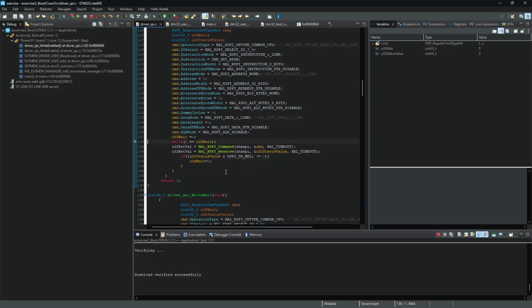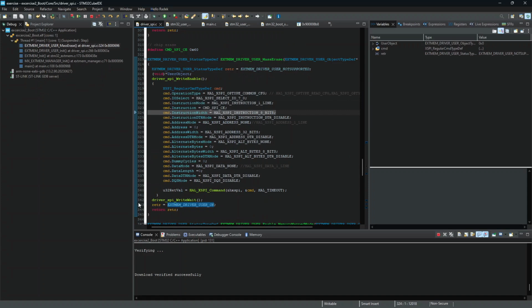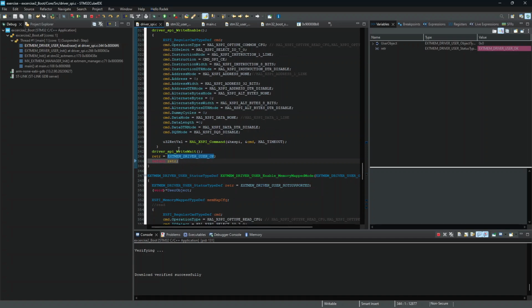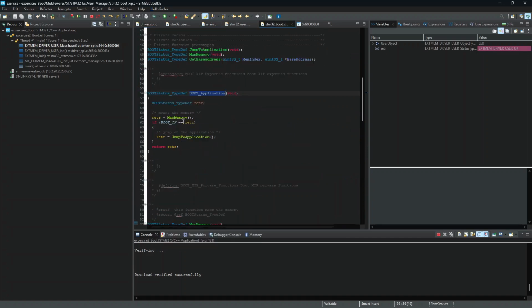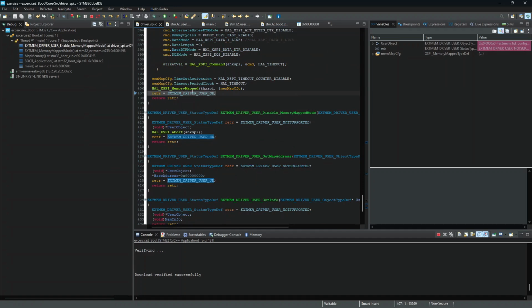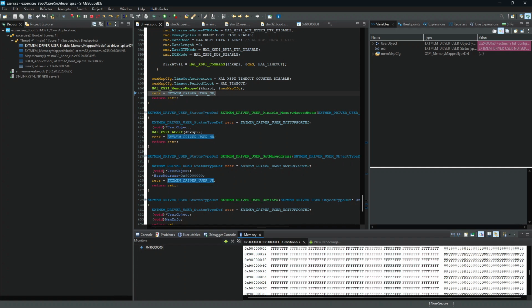So we can continue. It will stop waiting, and it can proceed with the erasing. So it will erase the device. It seems the device was erased because we left the wait. And we can go into the boot of the application, the memory mapped. I think I forgot that I put the breakpoint there, and we can look into the memory. And you see that the memory is completely empty. So it seems our mass erase is working perfectly, because it erased everything it could.